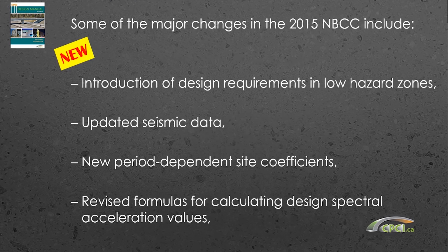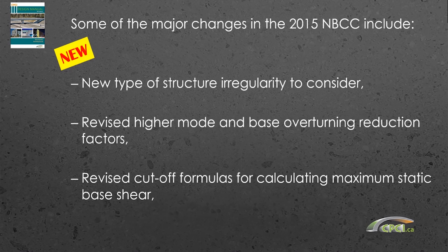So things that are new: there are new design requirements in low hazard zones. So for low seismicity, there are new requirements, updated seismic data, and a whole bunch of new structure period dependent site coefficients. I'll explain that. Revised formulas for calculating the spectral acceleration values. Added another type of structure irregularity. They've revised the higher mode and base overturning reduction factors, so I'll explain that, and also have changed the cutoff formulas for calculating maximum static base shear.